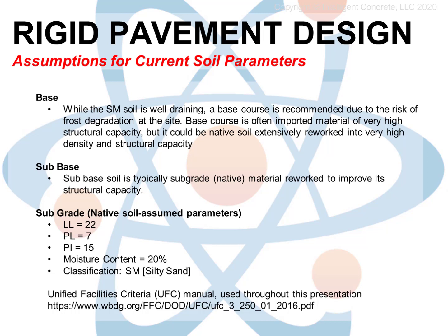Subgrade is the native soil. About the only thing we ever do to the subgrade is to roll it out smooth and flat and fill out or compact any low or loose areas. We dig out undesirable materials like rocks, stumps, or pockets of clay. Sometimes we'll scrape it up a little bit, add a little water, or let it dry out and roll it out flat again. But usually we don't do a lot to the subgrade.